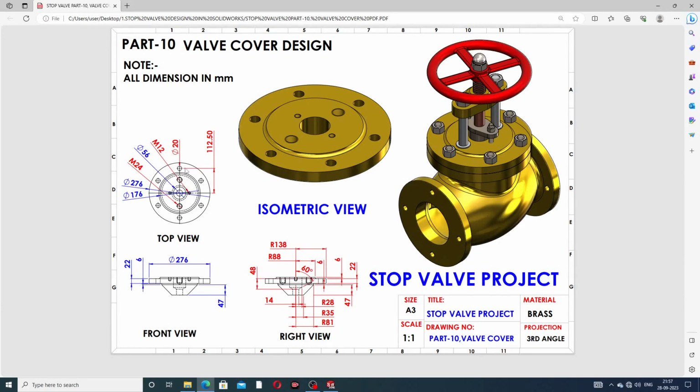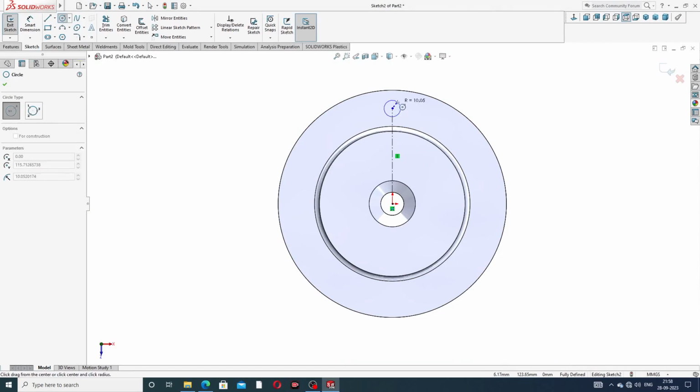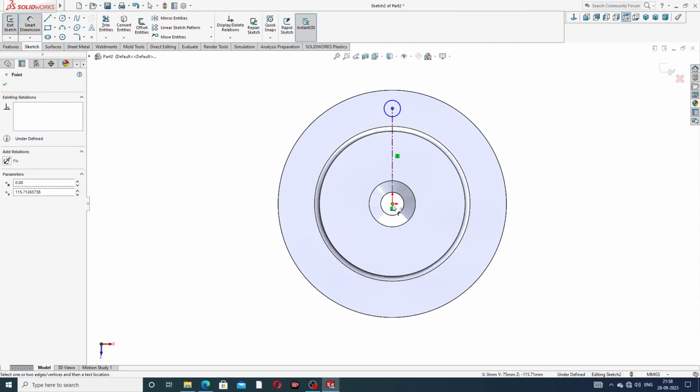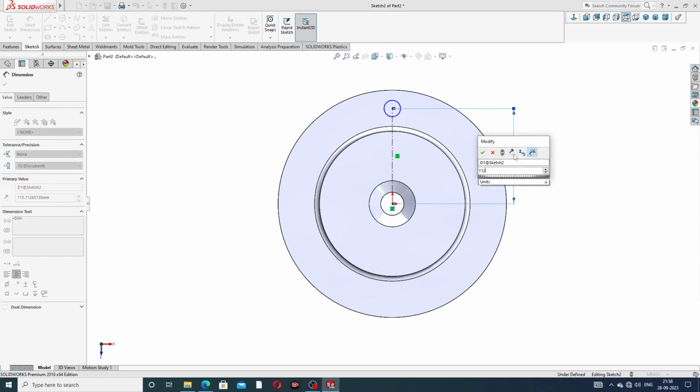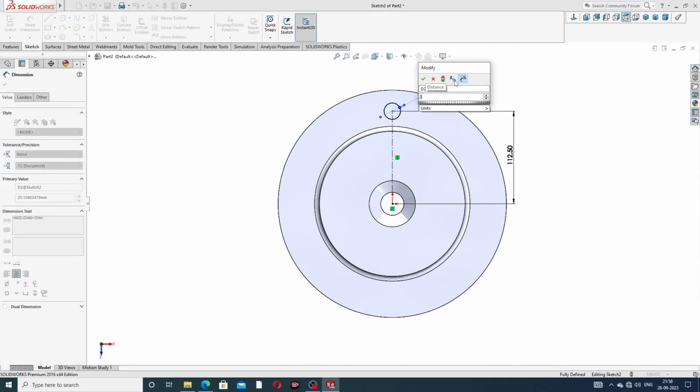Okay, and this is perfect and correct, and this distance is mentioned here. Apply a thread, and then distance is 120. Okay, and use a circle, drawing here. This is a vertical line, and this distance from this point to this is 112.5 millimeter, and this diameter is 20 millimeter.